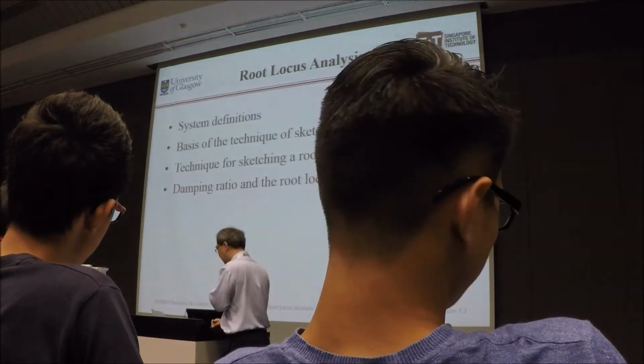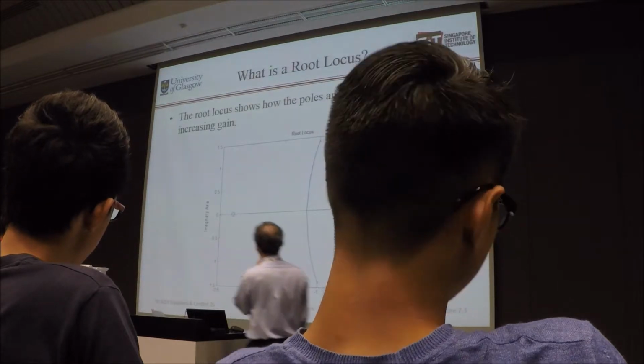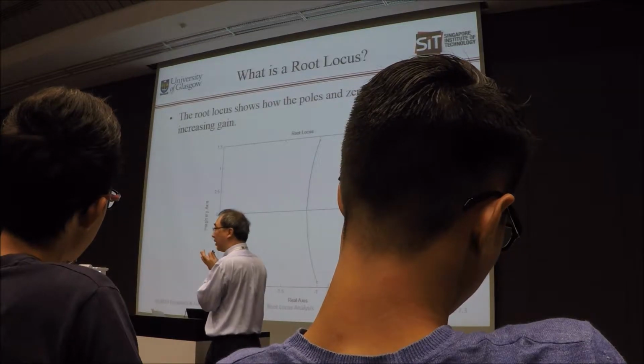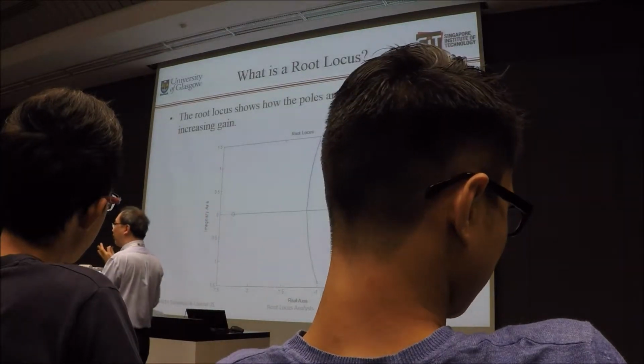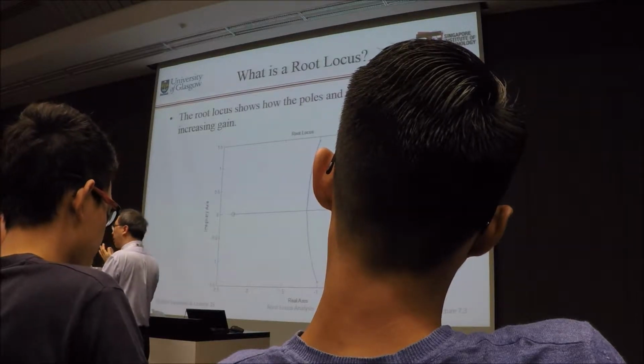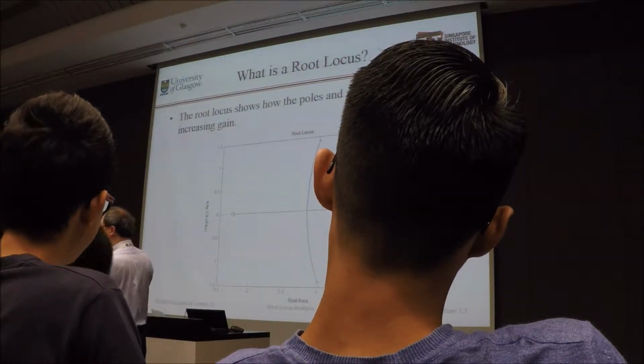Okay, all right. Let's take a look at all the basics. So this is how the root locus is going to look like. This is actually generated using MATLAB. MATLAB is quite straightforward: rlocus, numerator polynomial, denominator polynomial. You key it in, and this is what you will generate.